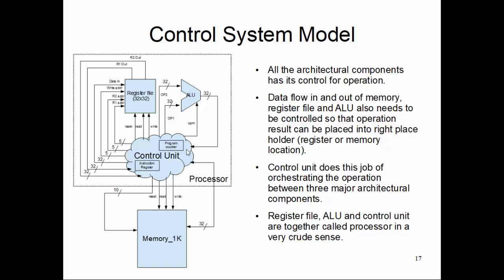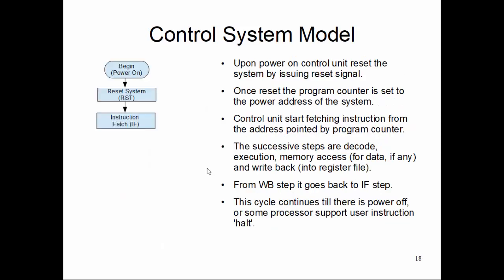It is different in an ARM processor system. If you look at the specification of each processor, it is defined there. This is a very specific, predefined value from which it fetches that instruction. Then it goes to the next instruction, and so on and so forth. It takes instructions from the memory location stored in the program counter.